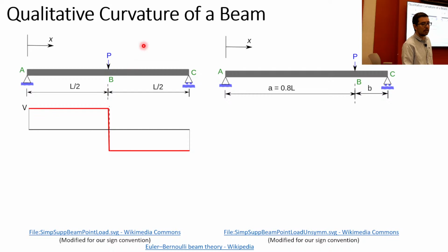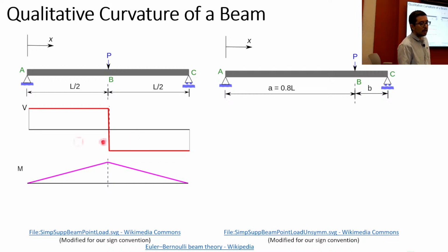This force P is going to cause a flip. And the internal shear force across it, you can see there's nothing happening. There's no distributed force along it. So it's got to stay constant until it gets to this concentrated load. This should be familiar. I could do this multiple ways, but one way we know is that dV/dx equals w, and dM/dx equals V. So you can integrate the V to get the M, if you so desire.